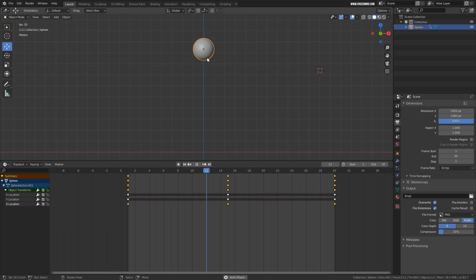You can not just place the keyframes but also adjust the time interpolation. I want this ball to work like a real ball. When it bounces, it should be fast, and when it reaches the highest maximum point where it can no longer escape gravity, there it should slow down. So we want this ball to be really fast till here, then slow down in the middle of the animation, and then come back really fast. That is how a real ball bounces basically.